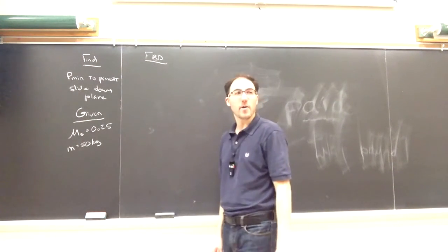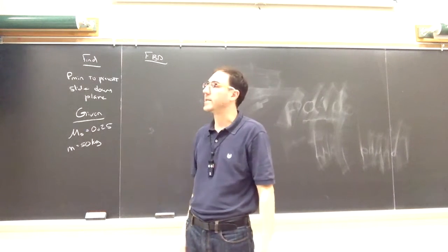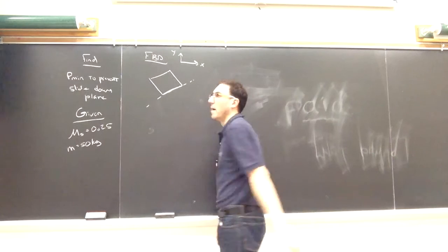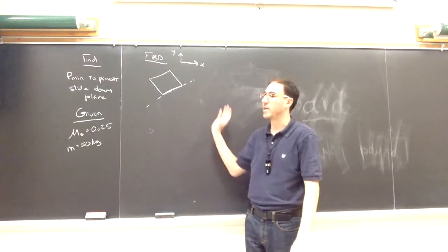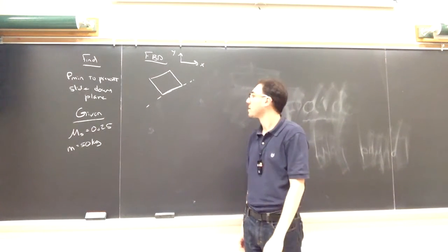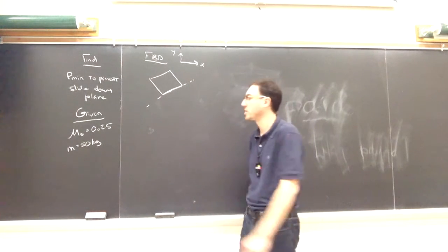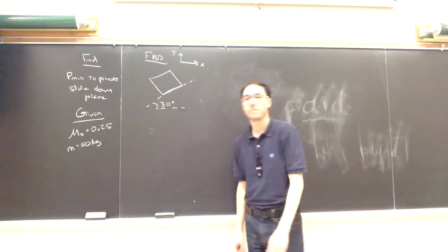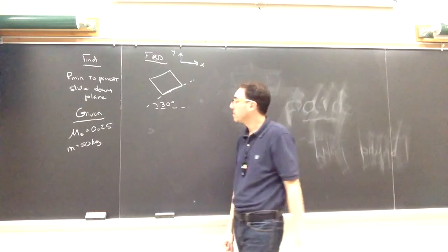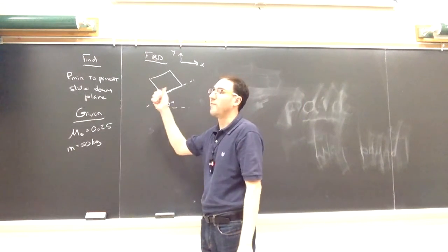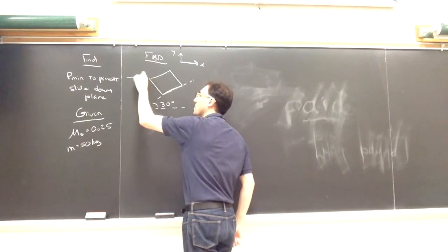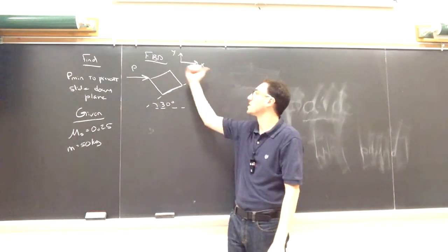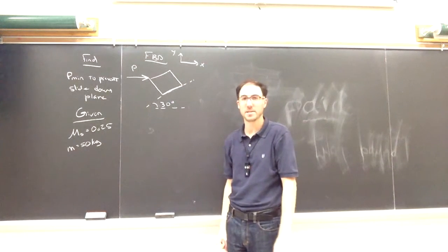In the free body diagram here, I really just have one object I need to look at, and that's the crate. I'm isolating the crate, so I'm removing the surface that it's resting on. But I will include just this construction line to help me write equations out of this. On the crate, I have one applied load, that force P, which in this case is completely horizontal, along what I'm calling the x-axis.